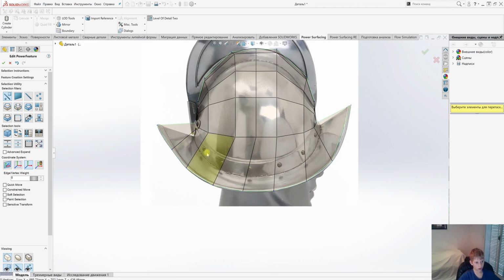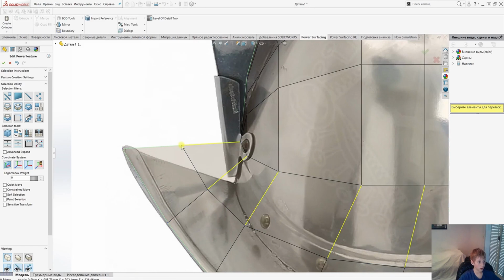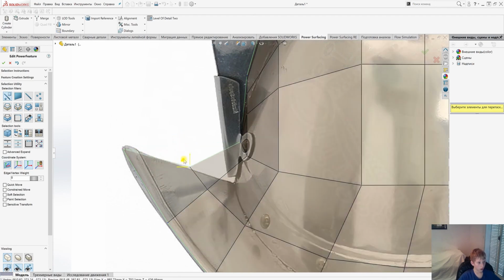Now let's create another division in our brims in the middle. For this, we'll use the ring command, which is the equivalent in 3ds Max. Click it and they get selected like this. Right click and choose connect. Now switch to point and edge in polygon mode and select this point. And continue moving our points, adjusting the shape to match the reference. That's it.